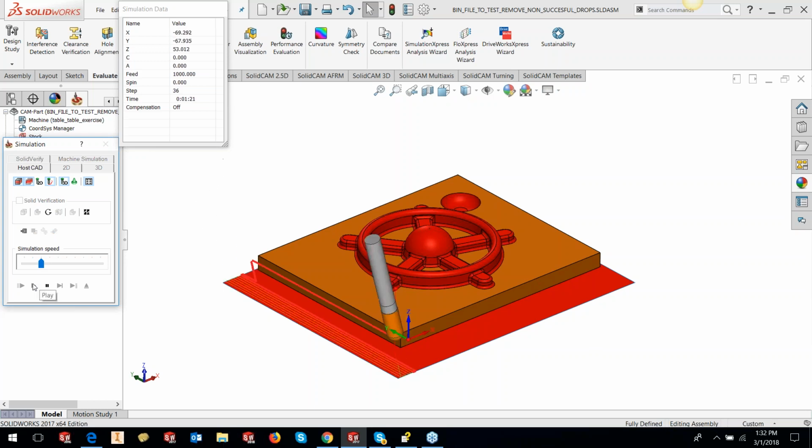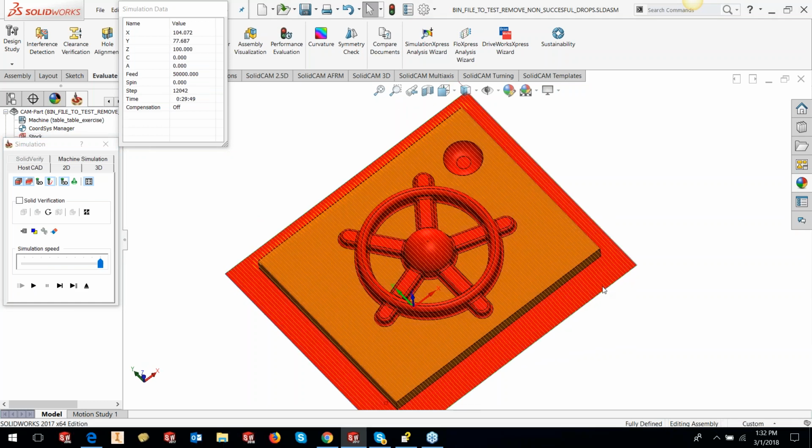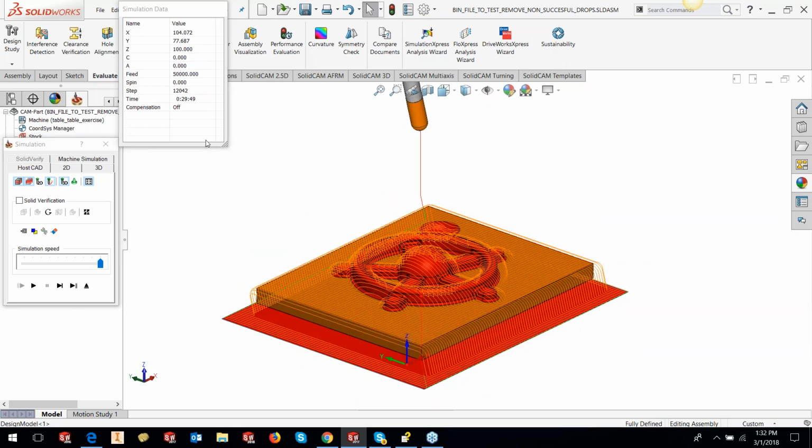What you can see now here is that it's actually machining, and as it comes close to the surface, it's now retracting the tool, because those are the surfaces that I asked to be checked for gouges. But I have got several areas that are actually not needed for me, because it's sheer waste of time that the tool goes all the way down, takes a step over and comes up. So I want to remove all those areas.